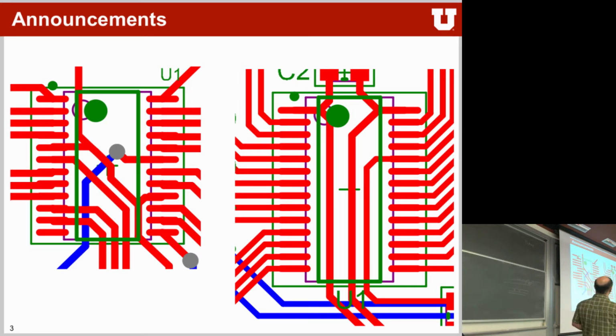And even if you route to the pad, if you hit spacebar, it actually changes the angle at which it goes into the pad. So sometimes you are at a 45-degree angle and you hit spacebar and it aligns it properly. But yes, oftentimes for pads in Altium, it's easier to route away from them than into them. So what I oftentimes do is I route out of a pad, go close to the other pad, stop at the location where I wanted to, go to the other pad and finish it that way around. But then yes, again, hitting spacebar helps you a lot in aligning and getting the right angle into it.